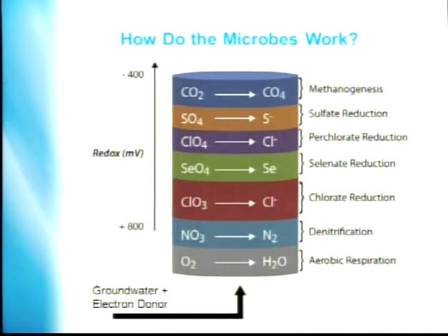We're all aerobes, and this is why we're very efficient macroorganisms. But some of these aerobic organisms also have the ability to be what we call facultative organisms, able to live in anoxic conditions. They don't need to have oxygen there, but they can denitrify. So they use the same process with that substrate. They take the nitrate and produce nitrogen gas.